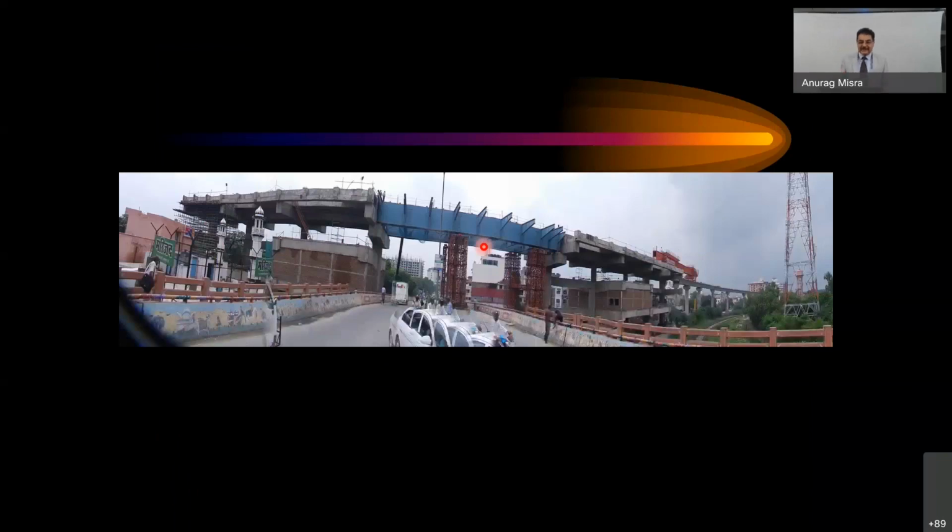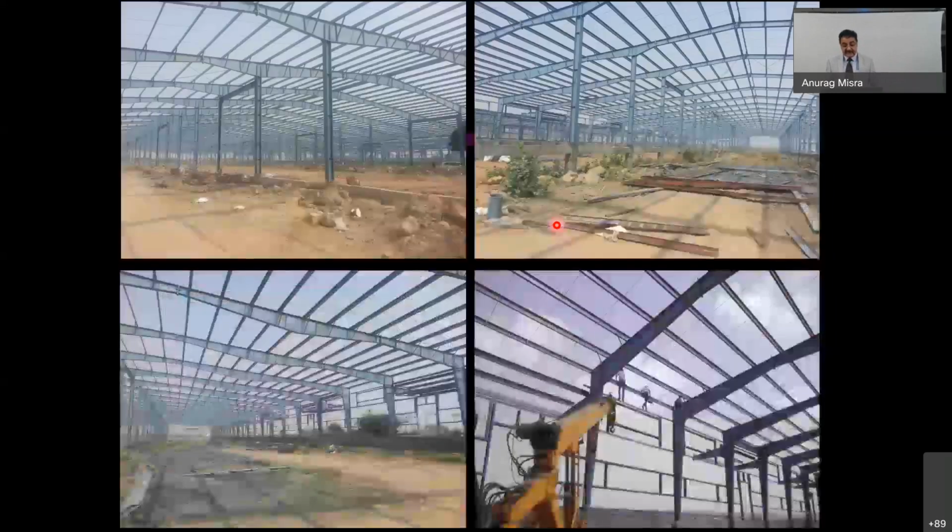So you can see that the cantilever members are coming out. This is just before you start putting the longitudinal members as well. So the girder is there, the main girder, one and two main girders, and inside between these two girders, there are cross girders which are attached to the bottom of these box girders, and the platform cantilevers are coming from the top on both sides, right? So they would provide the space for the platform. And you can see the traffic is continuing.